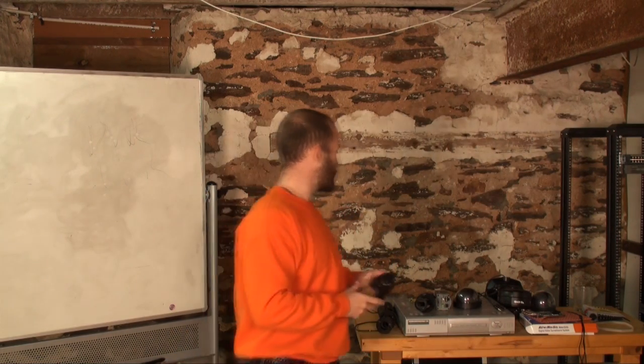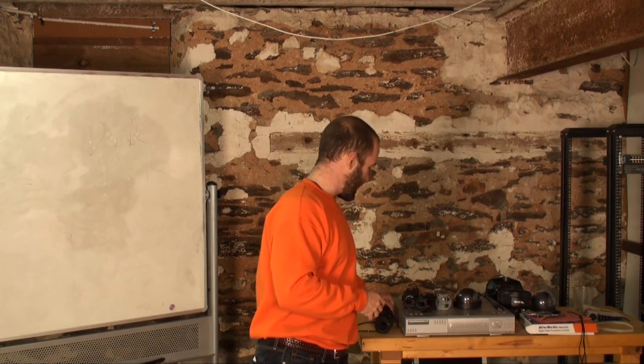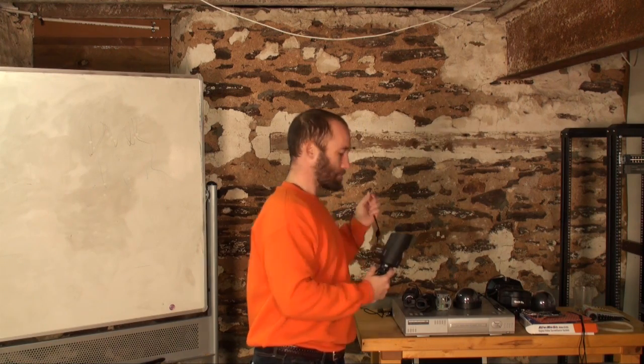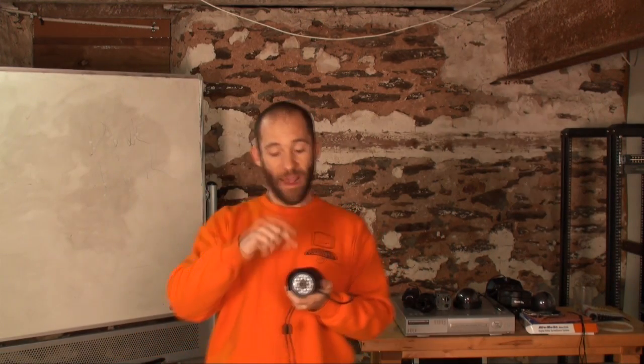You may also be interested in dealing with no light cameras. No light cameras are what are called infrared cameras. So if you're looking at this camera, this bullet camera, you can see all these little LED lights in here. These LED lights are infrared LED lights. What happens is this camera can see in the infrared spectrum, basically black and white in the infrared spectrum. Once the light level goes down below a certain amount, this camera turns on the infrared lights and then it can watch everything.